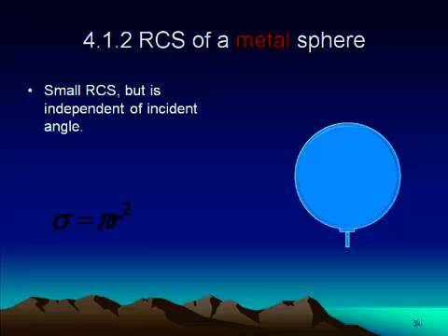We are keeping a cylinder before the radar and trying to understand how much signal will be reflected by this, and hence what will be the RCS of this. So here the RCS can be small for certain look angles, it can be large for certain other look angles. The sigma or the RCS of the cylinder is going to be 2 pi r a square by lambda, and mind you, it is only in a particular look angle.